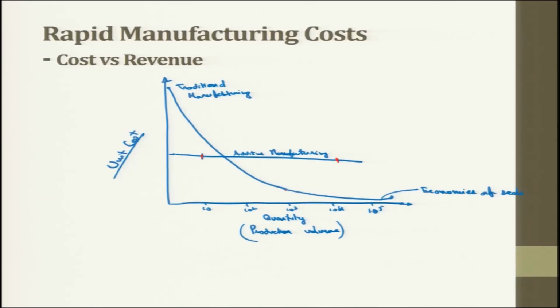But in traditional manufacturing, the setup can be made specifically because we have special purpose machines here. Here we have special purpose machines, and here we have general purpose machines. General purpose machines are like lathe, milling, drilling, machines which are general and can be used to do a specific operation on the job. A special purpose machine is like a bolt maker.